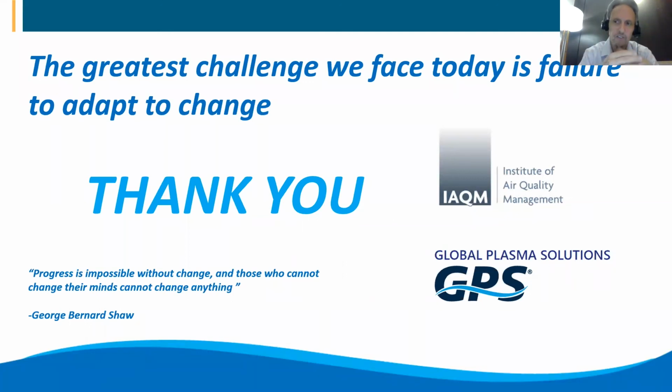But what it also does is it takes a surface that may have a certain charge potential, for example, negative, and by interfacing it with positive ionization, it will neutralize that surface charge. So there is less of a potential for those particles now to plate out onto surfaces, whether it be the wall, the ceiling, the floors, devices, et cetera. So actually it contributes to eliminating issues with the plating of particles onto surfaces, because we are maintaining those surfaces at more of a neutral charge potential now due to bipolar ionization.